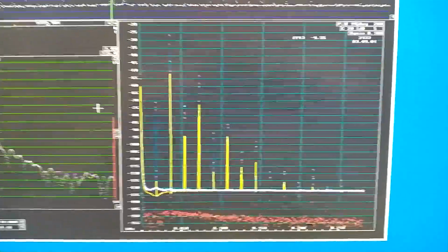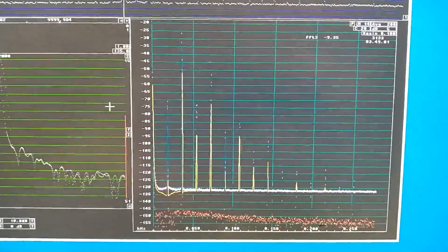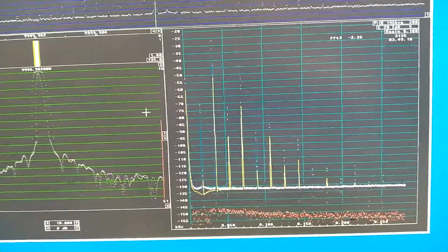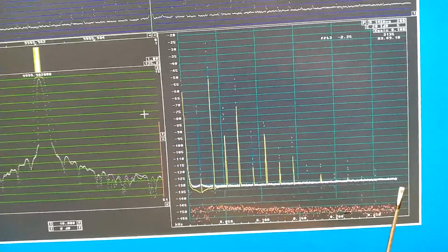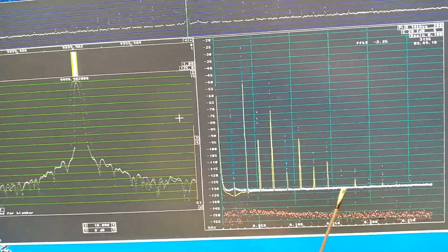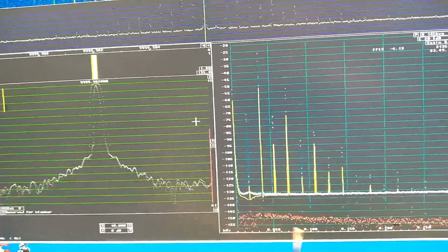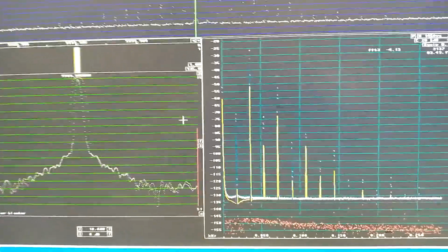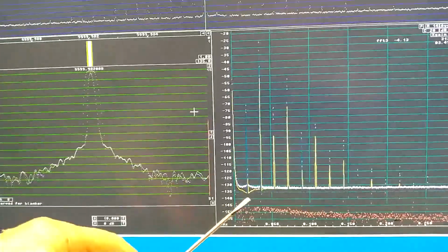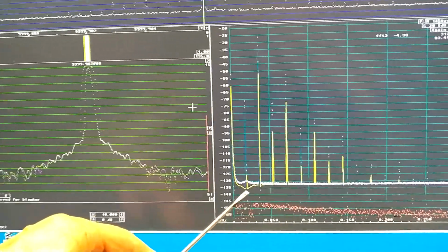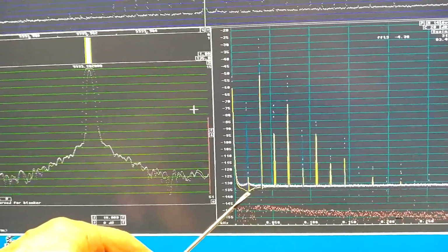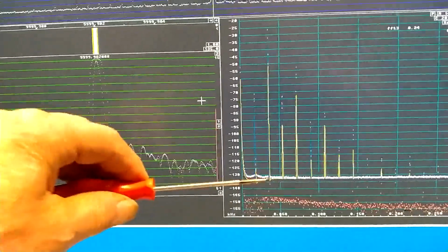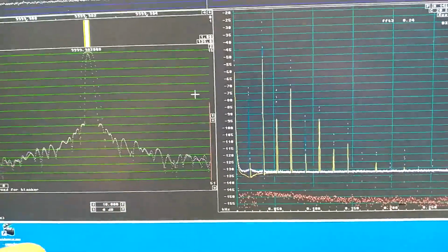I have switched from the SDR IP to a sound card, M-Track Quad, which is modified for this purpose. And you can see the noise that I am adding, it's the same as the previous with the SDR IP. It's added to the signal from the Wenzel oscillator. It is an interesting and not so pleasant thing to see that the noise drops below the true value. The noise floor I added is truly white noise. It should be flat everywhere.